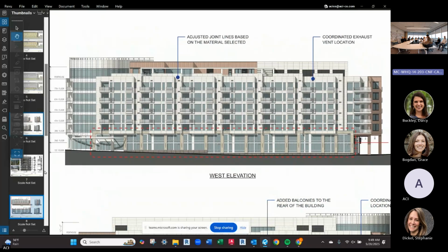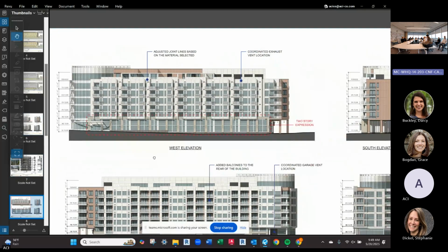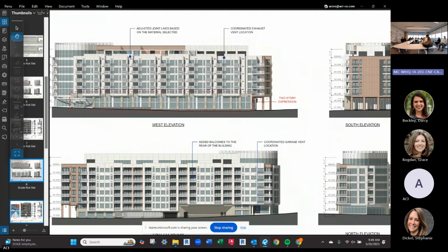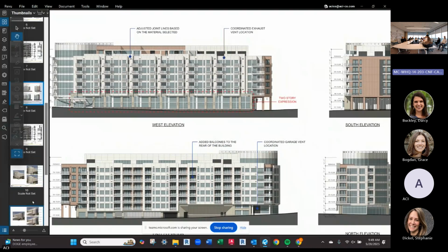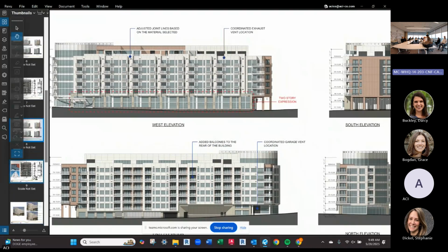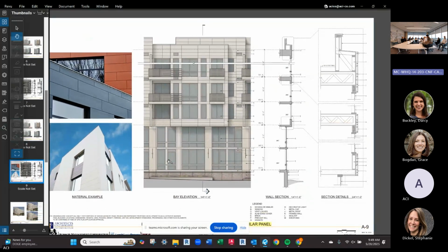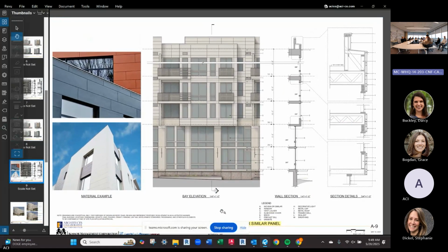So these are the two materials. There are many other materials, as you know, and we've looked at a lot of panels. The issue is they have different pricing, okay? They range, as you know, anywhere from $25 a foot, or like you hear $12 a foot, but that's really not the true cost of it at all. You're buying just the material, and then you have to provide the wall behind it. If you want to compare brick with brick or EIFS, you have to look at the whole cavity per square foot through the wall section.